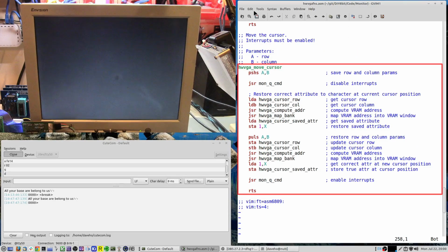The moveCursor function changes the current cursor position. This task is complicated slightly because the IRQHandler function, which handles the timer interrupt, also accesses the current cursor position, so moveCursor must disable interrupts in order to avoid a data race with IRQHandler.